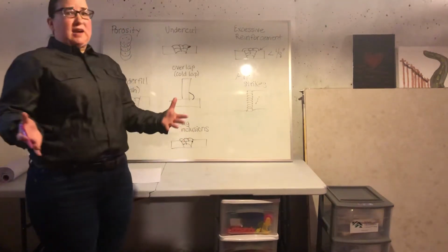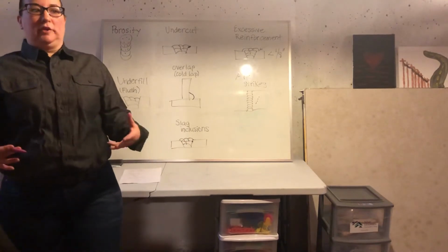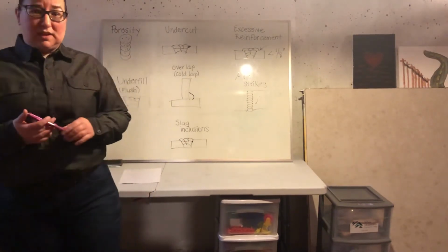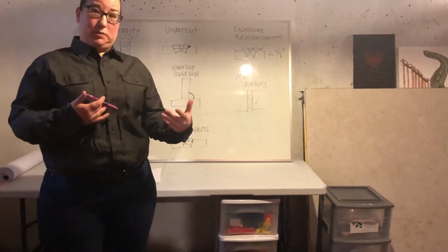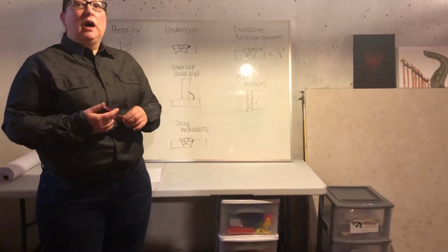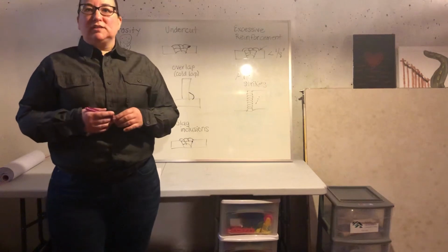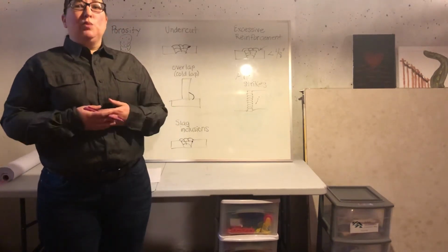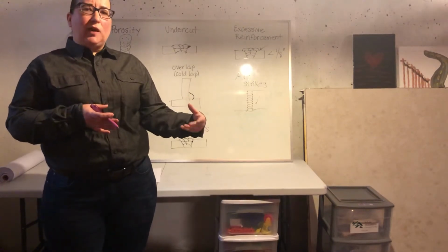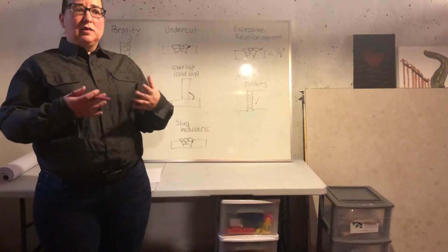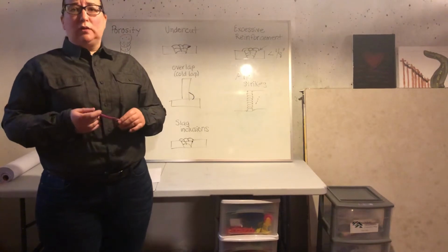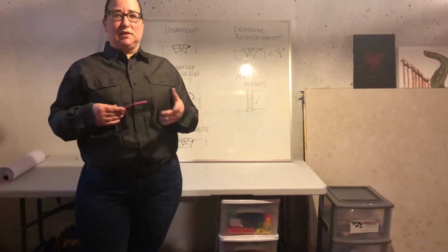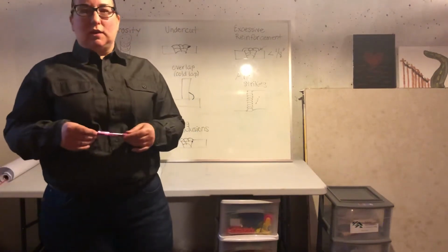So it all goes back to our power source, so the welder. We need to start with good settings. Things we can set for stick welding, we would control our amperage. For some of our wire fed processes, we would set things like our voltage and our wire feed speed. We'll talk mainly about stick welding today because it's the main process that most welders use, and it's also kind of the easiest to explain some of the different human errors that go into effect.